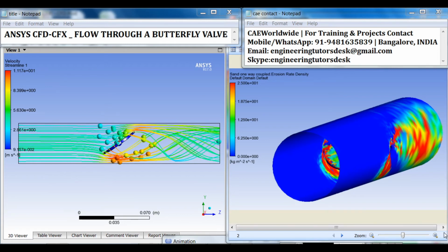Then we get into setting up a particle tracking simulation in CFX to trace sand particles. Afterwards, we need to consider initial settings for the problem and settings of solver controls before defining the run. And finally, animating particle tracks in CFX to trace sand particles through the domain after the solution is done.